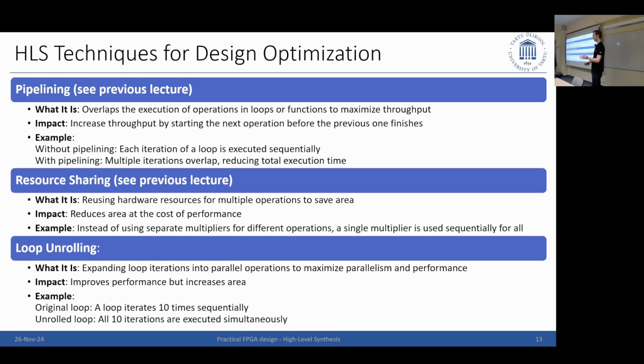What we do in pipelining, we do loop step 1, the process goes into step 2 of the loop, and when it's in step 2, we already start the next process essentially, which means that we might need more clock cycles sometimes, so it can increase our latency in some scenarios. We encountered pipelining previously for more flexibility, for timing optimization, but here it can also very much be used for throughput, which also applies for VHDL, of course, that it also increases throughput if you do it well.